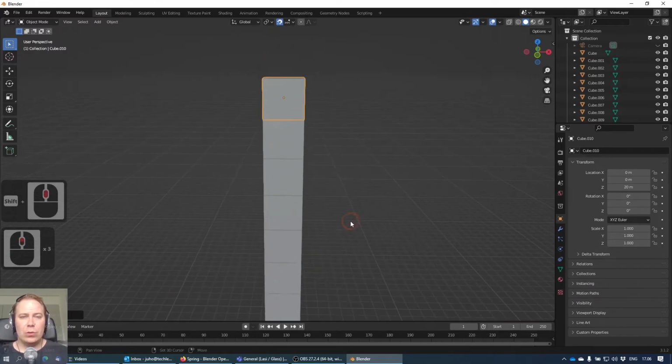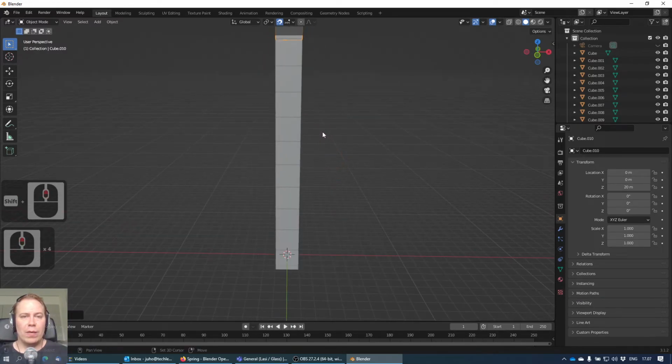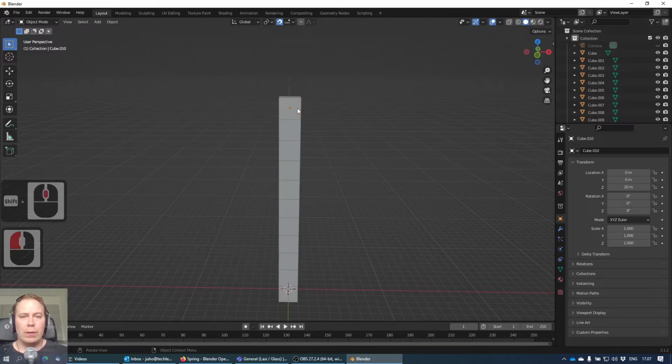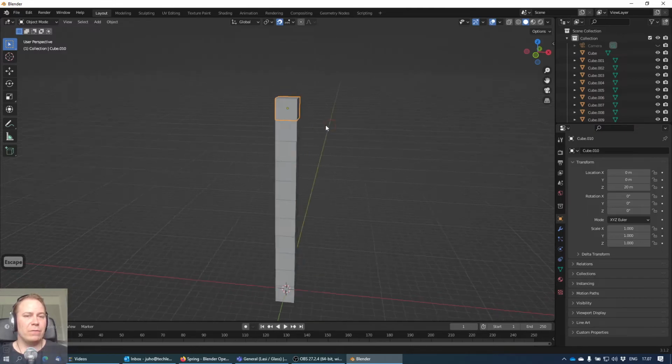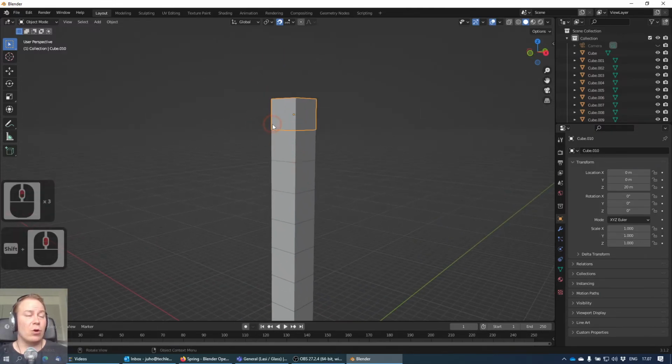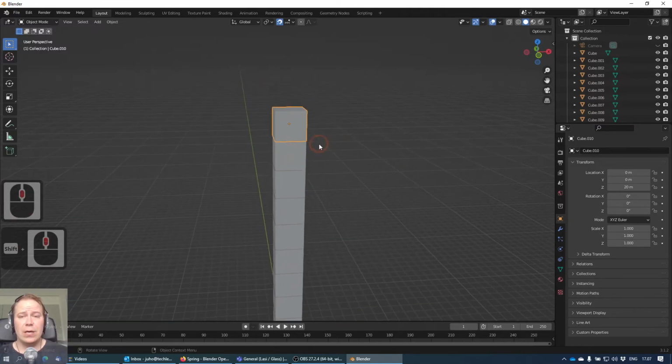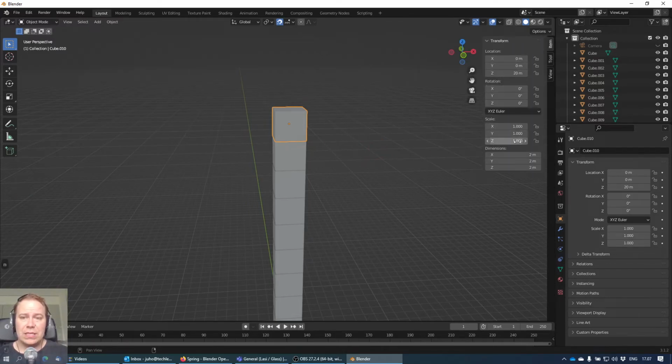We want to aim to do a Roman style of pile, so we need to make this bigger. You can make this bigger by clicking on S, but that's not a very incremental and correct way of doing it, because some of the vertices and models are overlapping, and that's not good in 3D design. So if you click on N, you can see that all the scale menus per object are located here.